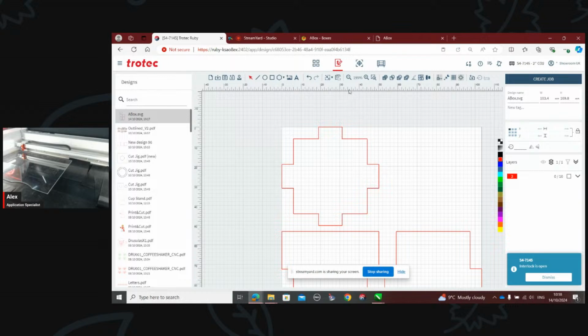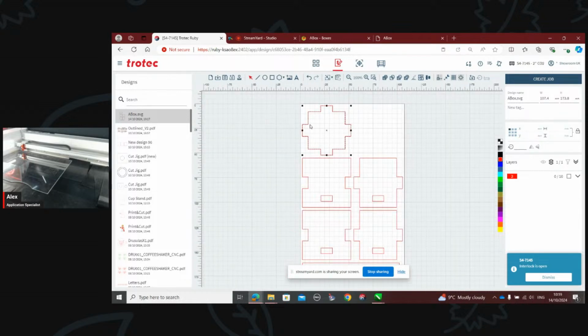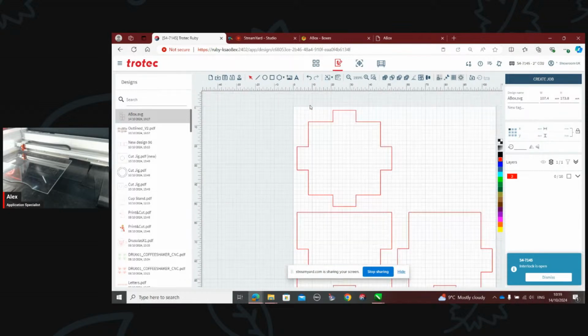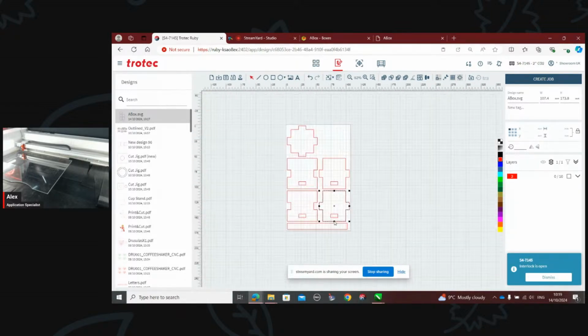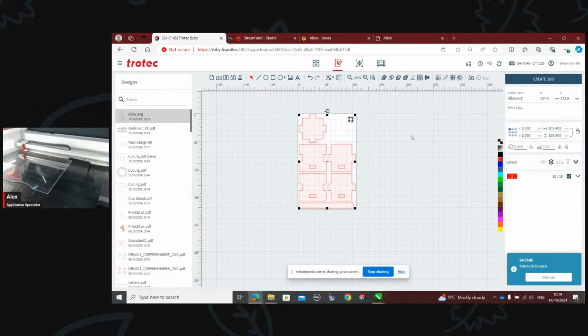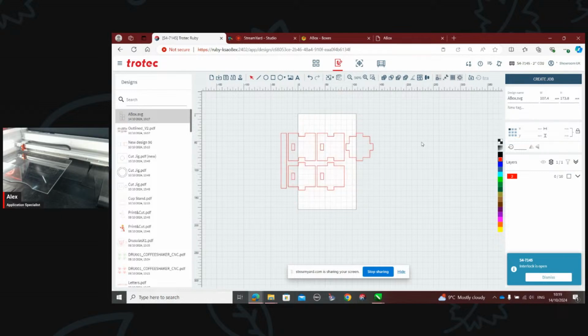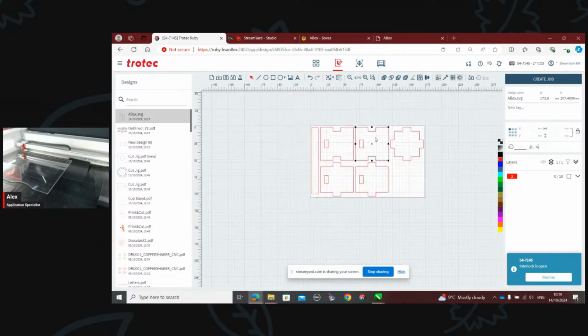And then you can update this to have a 2mm border. So that way, if I snap my job right up against my rulers, I'm going to have that exact border I want to match your cut paths. We can also do some other basic processing. For example, you may bring in the artwork and you may actually just need it at 90 degrees. So you can easily do your basic rotations and things like that in the software.